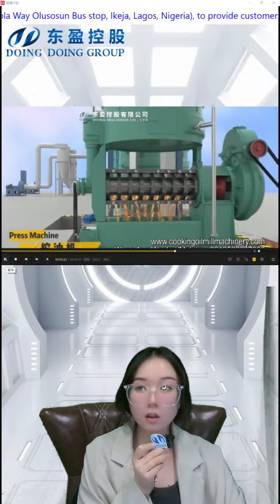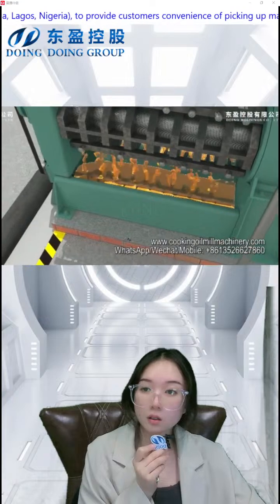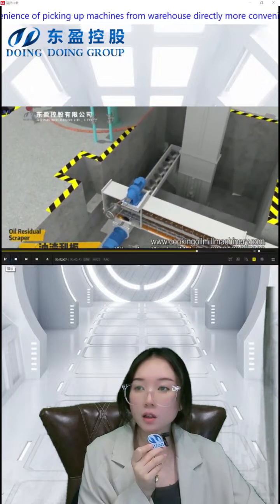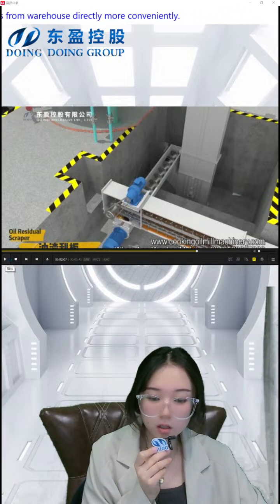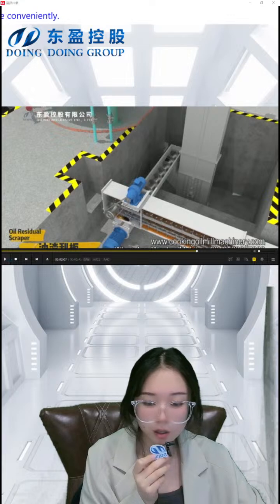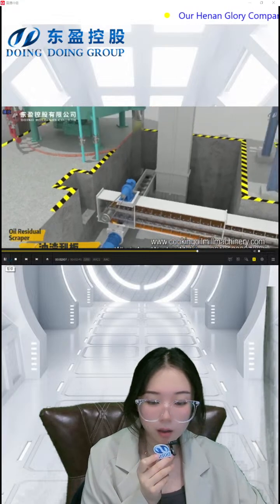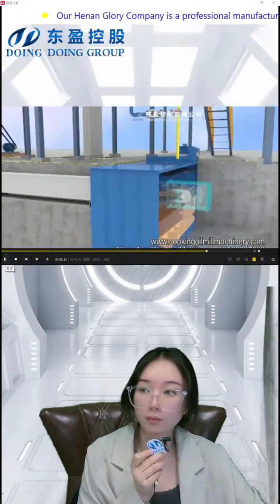And then we can go through the filter section. There are two machines in our filter section. First, the oil residue scraper. The function is to transport the settled oil residue from the crude oil transportation process and the oil tank to the bucket elevator. The bucket elevator returns it to the oil press, so it can press it again.